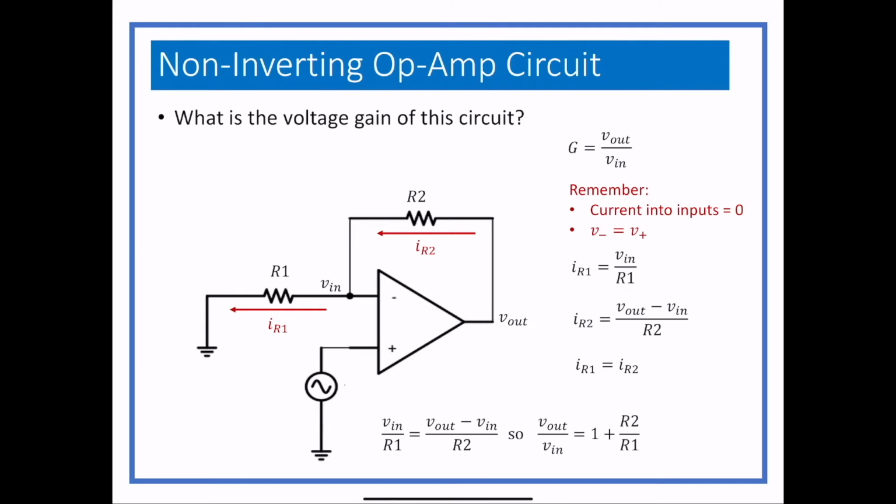For this type, a non-inverting type, the lowest possible gain you can have is 1. You can't ever have less than 1. If you were to completely eliminate R2 and R1 out of the circuit, you would have a feedback loop that, and we'll cover that in a minute, would give you a gain of 1. But that's the lowest gain you can have for a non-inverting amp, is 1. So that's the gain for a non-inverting amp.